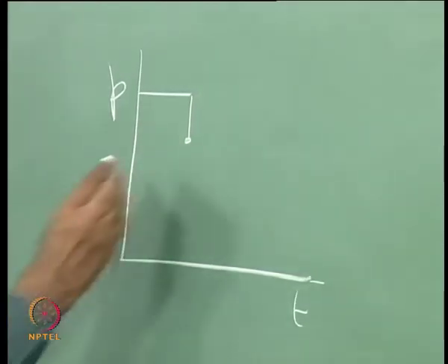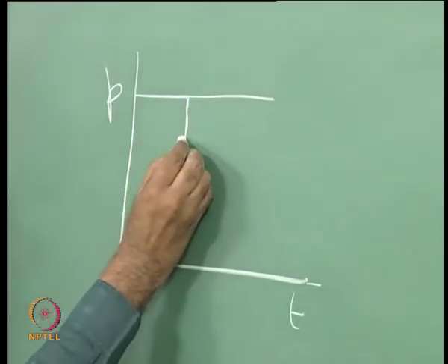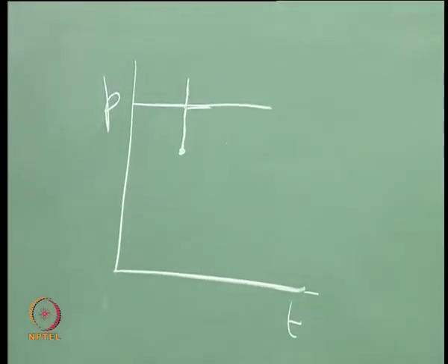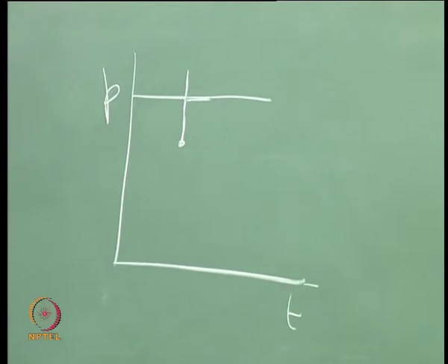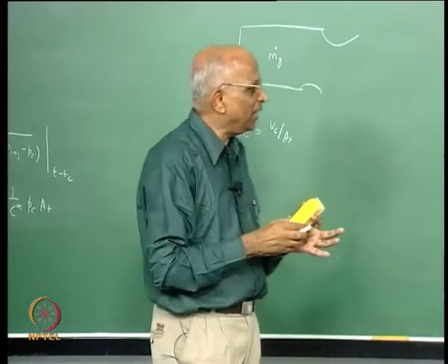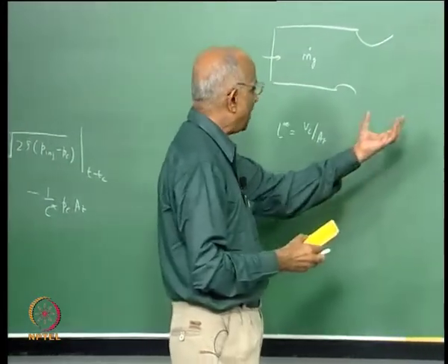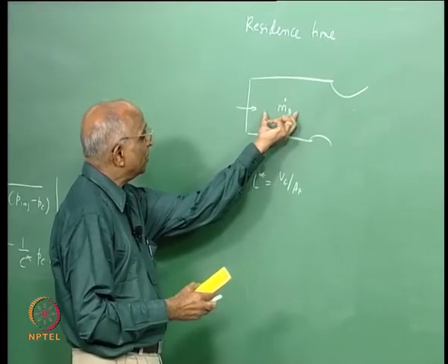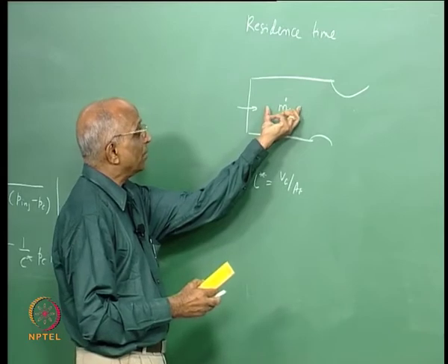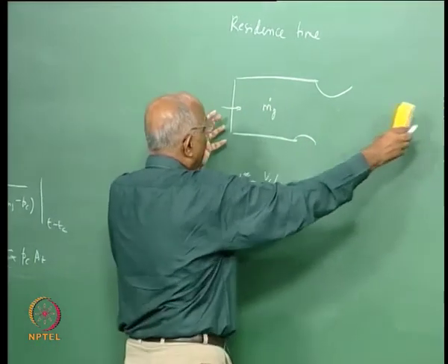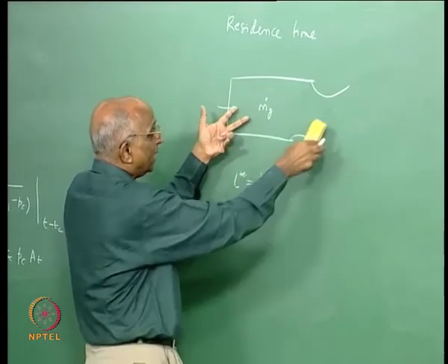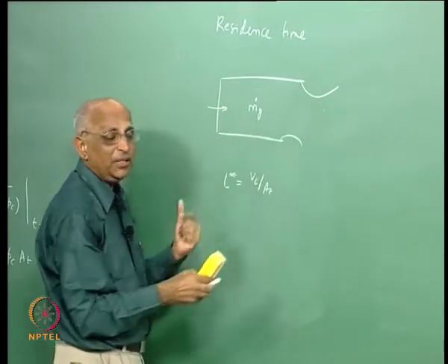What is going to happen? It goes back here and adjusts, goes back here, adjusts. Therefore, without a time delay, I cannot think in terms of these oscillations. And what is the role of this time delay? Well, the same thing, there is a lag and that is what causes it. Now, can I compare the time delay with respect to some other time here? Because if I have a very large chamber, maybe my time delay, which is still the same value, I can still accommodate it and it may not give me that problem.